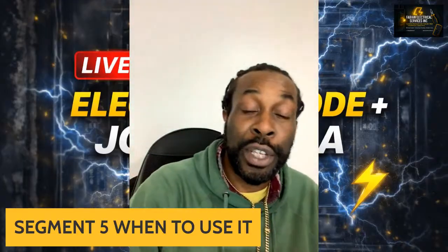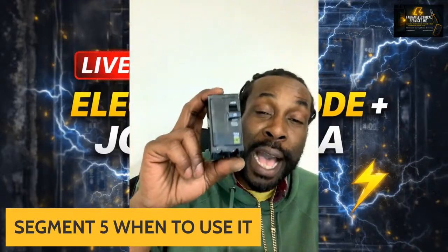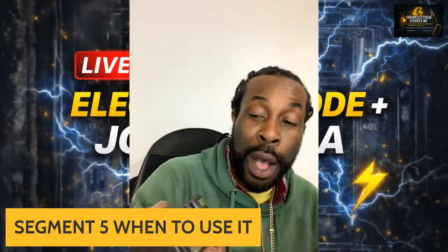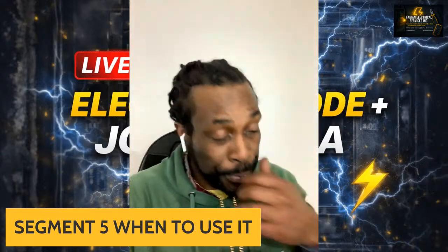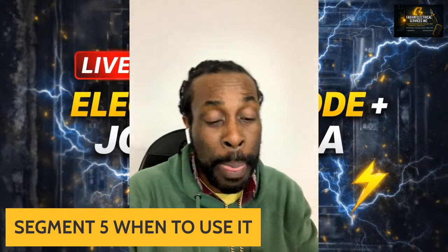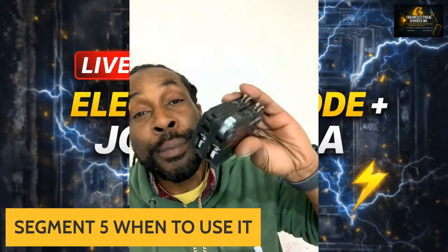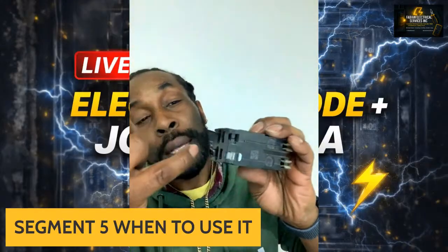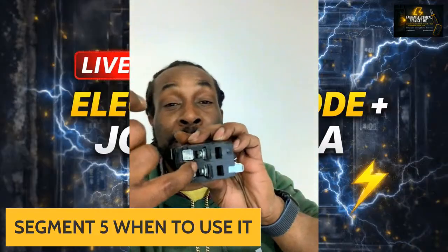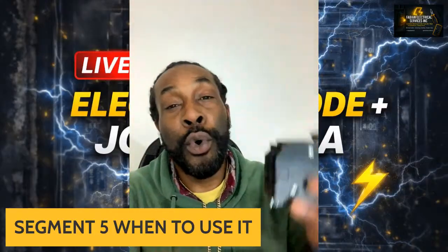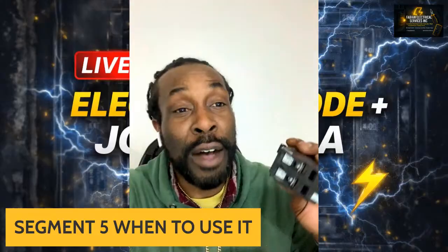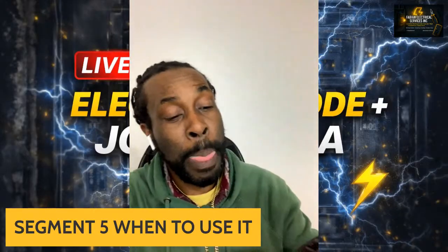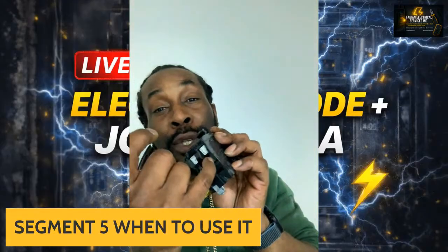This is actually a 20 amp two-pole breaker. So what can fail inspection also is improper connections. When it comes to your breaker, you want to make sure that you have the proper wire that's going to fit in here. You don't want to oversize the cable itself. Again, some breakers you have to pay attention to when it comes to connecting your line here.